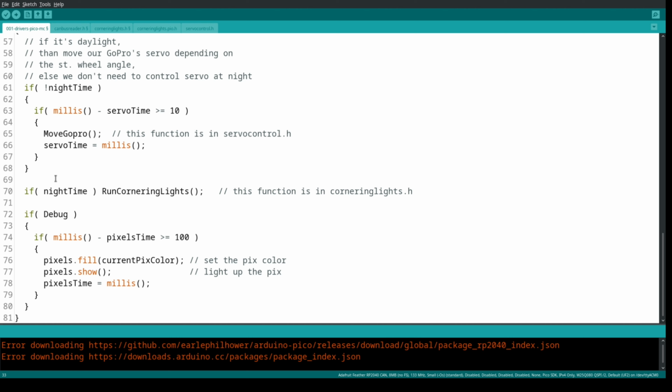And for this reason, when I was looking for turn signal values with the SavvyCan, as you saw in the first video, I did so by not switching the turn signal indicator, but instead only touching it, left and right. And I simply forgot to work out the values for this frame when the turn signal switch is not just touched, but also switched on.